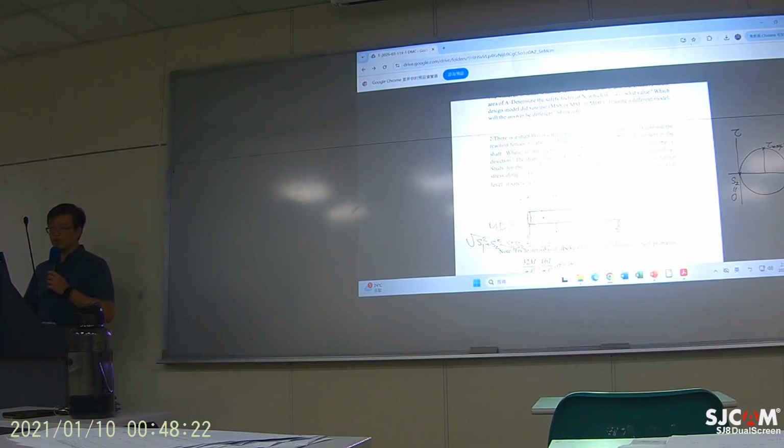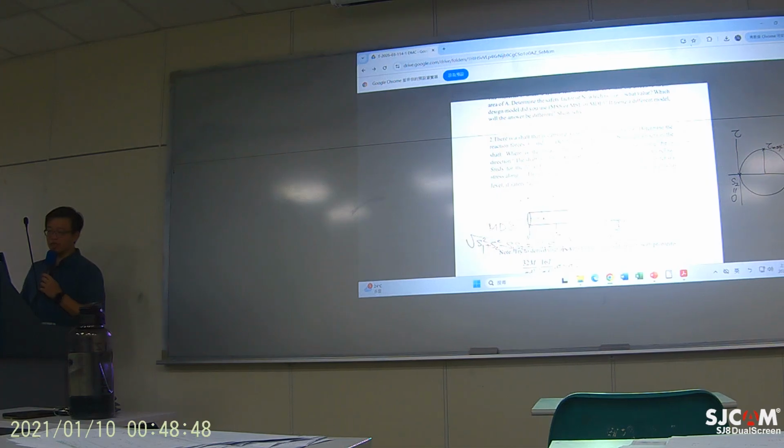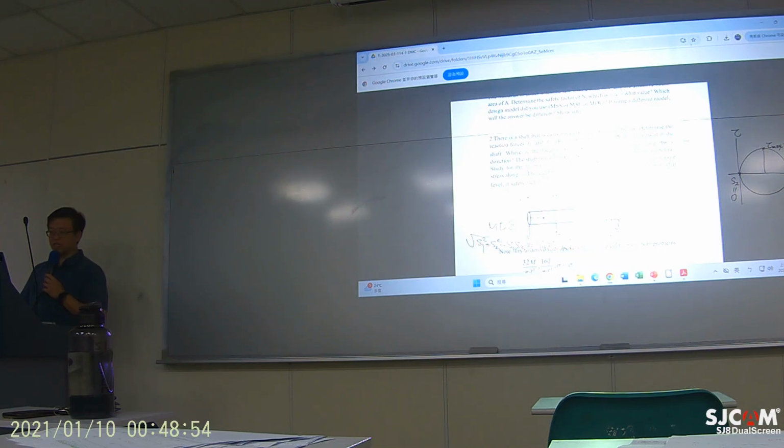Determine maximum bending moment. Where is the location of the largest tensile stress along X direction? So somewhere that is being pulled from left to right. Where is it? The shaft is also being twisted by a torque of T, as shown below, and then study the first and second principal stresses at that position with the maximum tension stress.